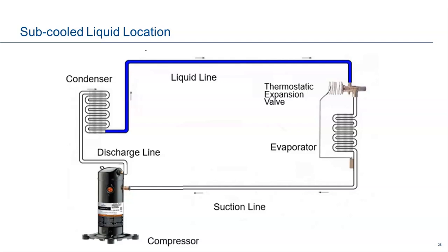I want to also take it back here, all right? I like taking it in both places. For one reason, in residential, you're going to have some place to take a pressure reading. And I said 6 inches earlier, in residential it's not going to be realistic to be able to take a pressure reading. But I can tell you the difference is going to be minimal, okay? But if it's major, we want to start looking for maybe a kinked line set, okay? Or maybe somebody at 5 o'clock, beer 30, if you will, on a Friday, just took a piece of copper off their truck because they were missing a piece here and just cobbed in a small piece that wasn't right, going back to those restrictions we talked about earlier. Okay, so take them in both places. We want to confirm that we've got liquid all the way to the metering device.